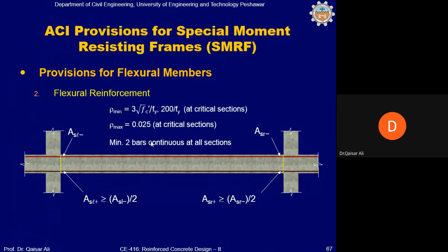So for this reason, it is quite possible that sometimes you may obtain bending moments even larger than the bending moments at the midspan on the bottom side of the beam. In order to make sure that some minimum reinforcement exists on the bottom side of the beam at the end of the beam, the ACI code has placed this restriction.